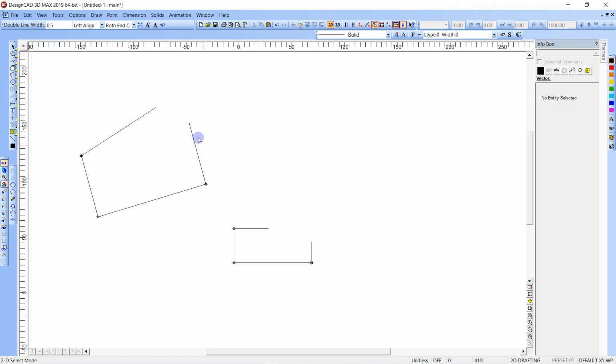But if I want to shorten that, let's say I don't want it to go all the way, say a V, Control K, right there, right? I want it to stop. Let's say I wanted it to stop right in line with that. Then I just hit Shift underscore, which is right next to the 0, or Shift dash, right? Hit that, and then right click there, or hit Escape, right? Anywhere that's close enough that it recognizes that's the line, and then I can right click there and it'll trim it to there.